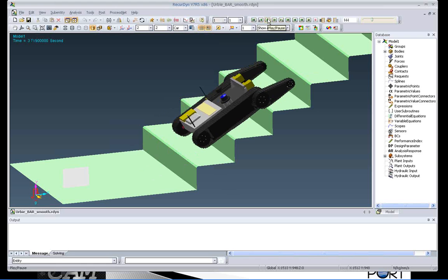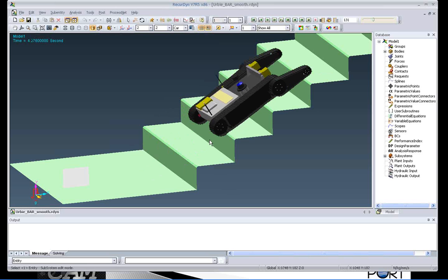These are ways to use simulation to obtain the load data that you might want to use to look at different components. And as you study the load data on the system, that also helps you identify which components deserve more attention, because the components that are seeing the higher loads probably should be looked at, rather than the components getting lower levels of loading, given that they're maybe made of the same material.